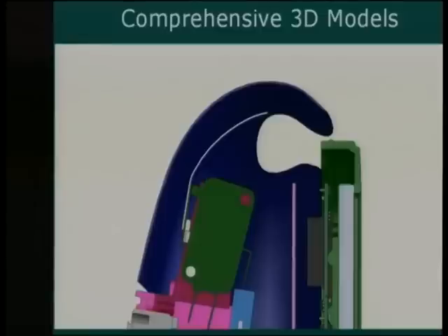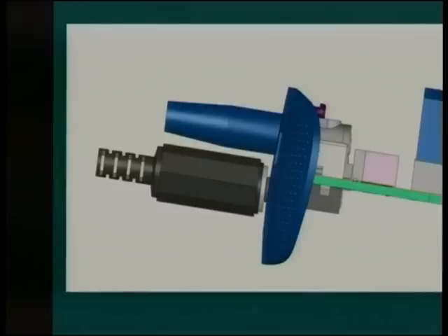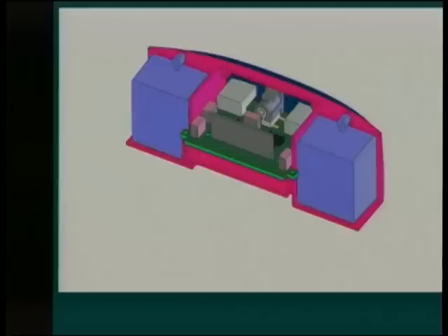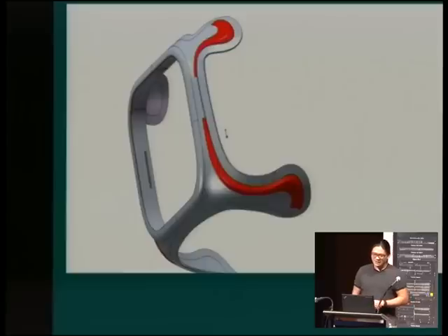So every design that you want to manufacture starts with a very detailed 3D model. We would model the circuit board and the parts on it, all the connectors, all of the holes, cross sections, the clearances, everything would be done in a 3D model environment. It's very important to make sure your connectors don't collide before you actually make your product. It's sort of unfortunate when they do, so we would take time to make sure that's okay. Make sure the LCD doesn't fall out, make sure the speaker boxes sound good and they're the right size and so forth. So we did a lot of modeling and CAD work.